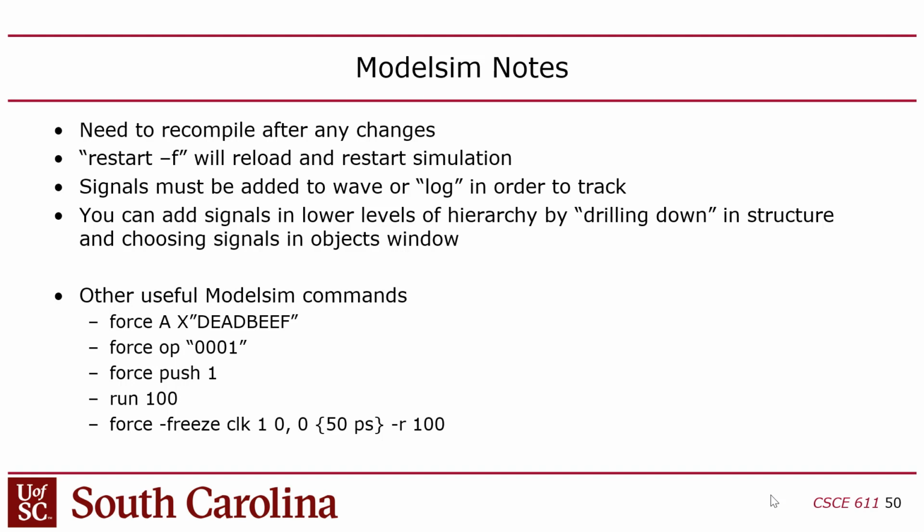Now, ModelSim is actually capable of modeling logic delay. I've done this before, but it's really tedious. You can place and route your design on the FPGA, and then you can pull data off of that compiler and backfeed it into ModelSim, and ModelSim will then start behaving like the FPGA does in terms of delays. It's kind of cool, but it's not practical. No one ever does that.